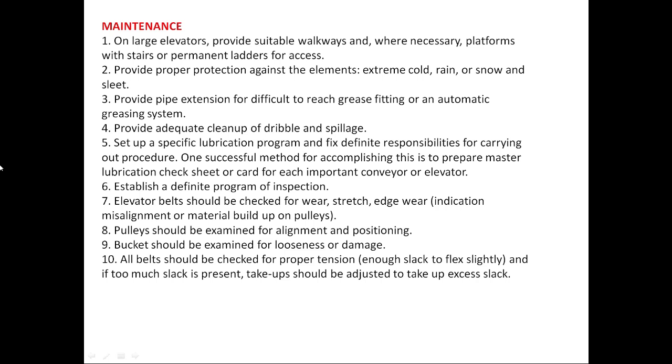Provide adequate cleanup of turbulence and spillage. Set up a specific lubrication program and fix defined responsibilities for carrying out the procedure. One successful method for accomplishing this is to prepare a master lubrication check sheet or card for each important conveyor or elevator. Establish a defined program of inspection.